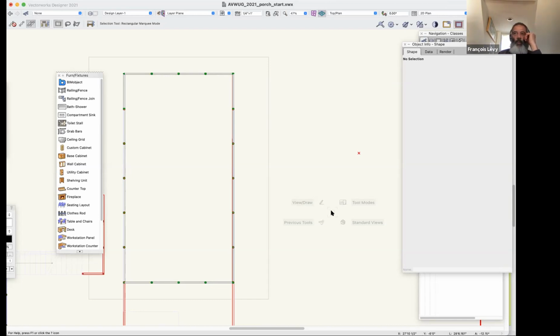So that ended up being just a wall style where there was a component that was essentially a landscape wire hatch, or texture rather, like a 2-inch wide by 4-inch tall grid instead of a 4x4. And then there was a 2D hatch associated with it so that it appears correctly in hidden line views like you would expect for CDs.